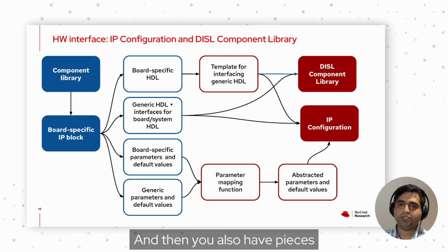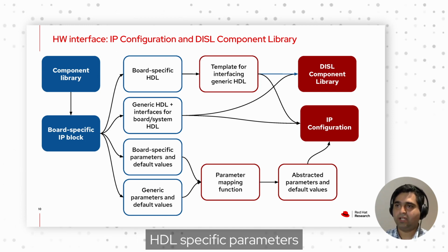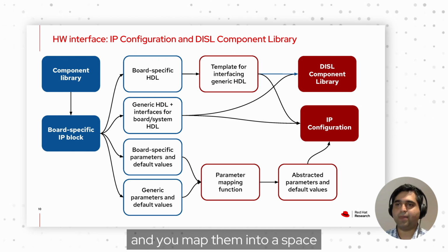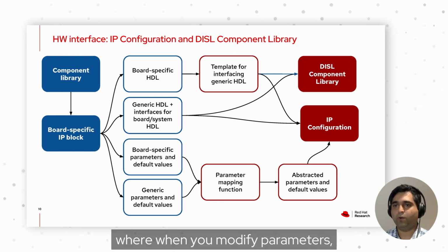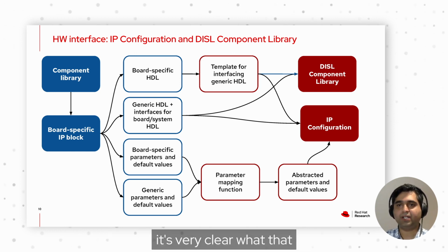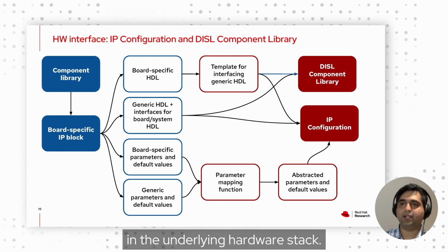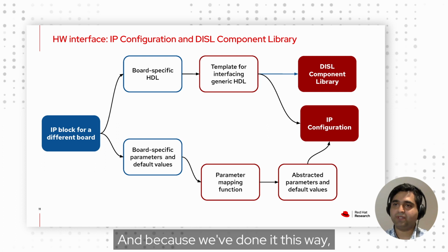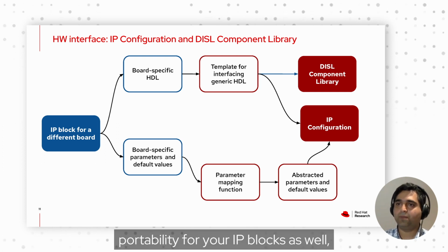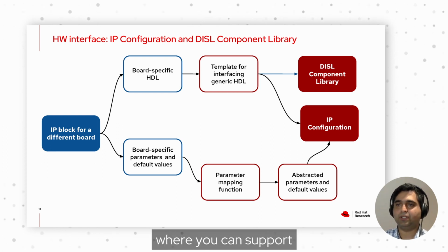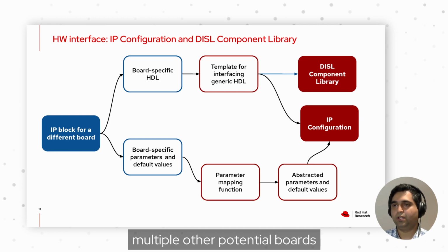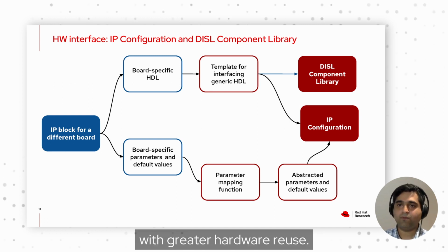And then you also have pieces where you take your HDL-specific parameters and you map them into a space where when you modify parameters, it's very clear what that modification will result in the underlying hardware stack. And because we've done it this way, you get a lot more portability for your IP blocks as well, where you can support multiple other potential boards with greater hardware reuse.